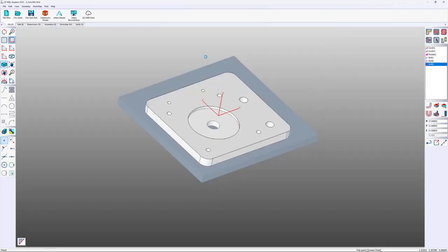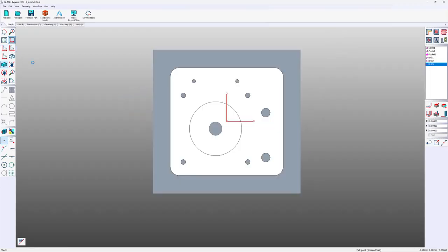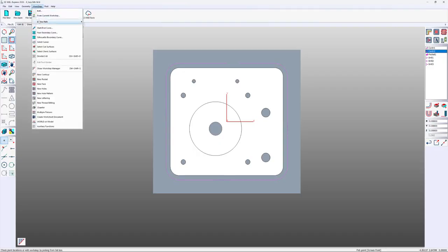Okay, now it's time to get rid of those tabs. So I have to create a boundary curve. Then I have to trim so that we machine just the tabs. So let's go here. Okay, so I need to create, I'd say we'll give it a little bit of an overlap, come in, then wrap it over to the next tab. So the way I'm going to do that, it's a little bit of work. We'll go with a silhouette boundary curve.